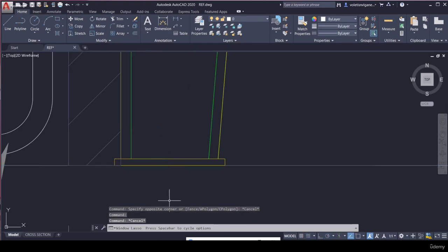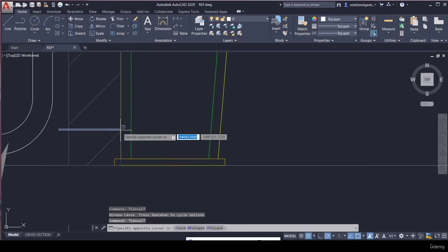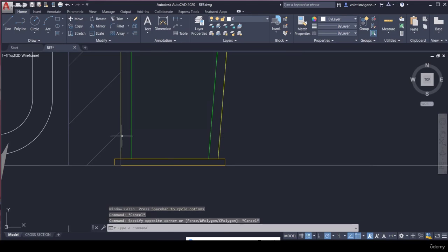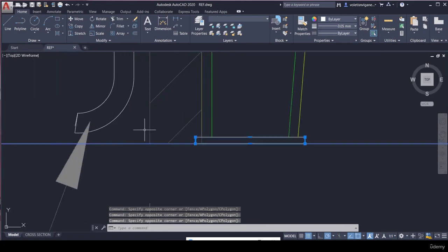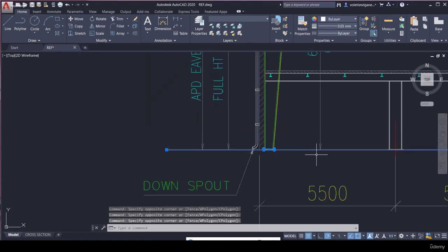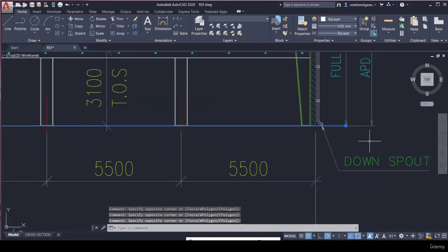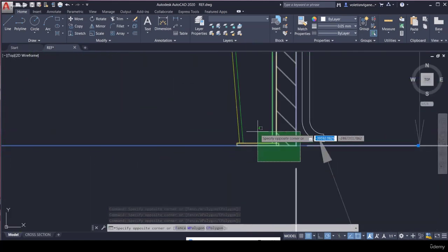So the block wall will be 200, and the center line will be, for example, if we take the column base as 400, 200 plus the center line 200. You have to subtract 400 on each side while giving the STAAD property. Okay. Did you get it now?